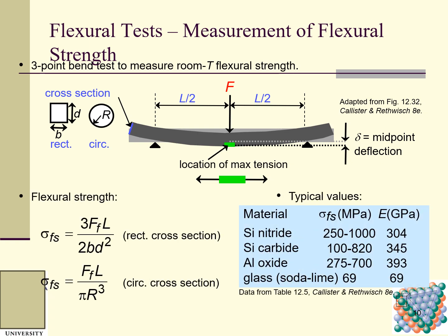Fracture strength can also be calculated using this 3-point bending. And so these are typical values for the commonly used ceramic materials. Sigma is the fracture strength, we call it fracture stress, when the crack starts initiating and propagating. So here is the Young's modulus.